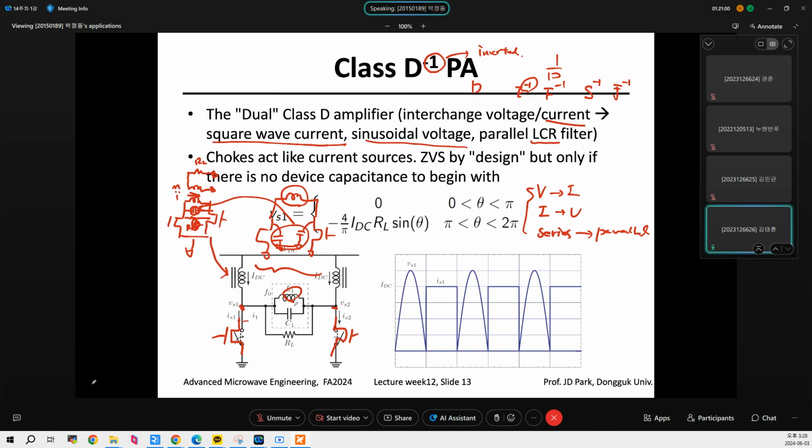This voltage is sinusoidal in AC terms, because it is high at omega zero, and for other frequencies it becomes low. So that makes sense. The parallel network looks like this, right? Impedance-wise, at omega zero, and at 2 omega zero or DC, this is a short, which means there is no voltage between the two. So the output is definitely sinusoidal because of this resonance circuit. So the output voltage is sinusoidal. Check.